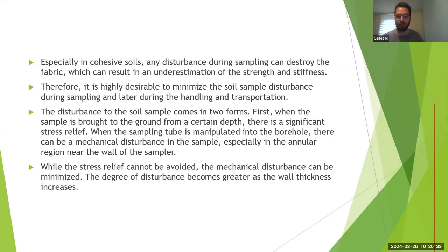Generally, it's really hard to minimize those stress reliefs. But what we can minimize is the mechanical disturbance of the sample. Especially, we can use thinner walls of the sampler. So that would generally minimize the deformation of the sample.